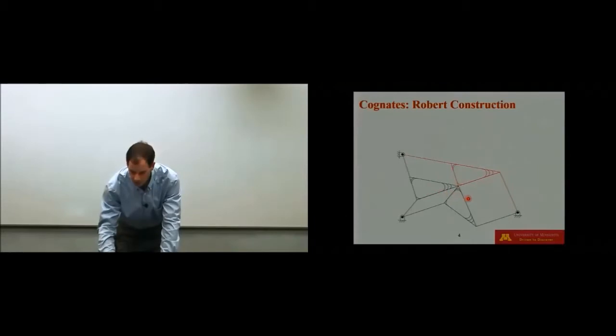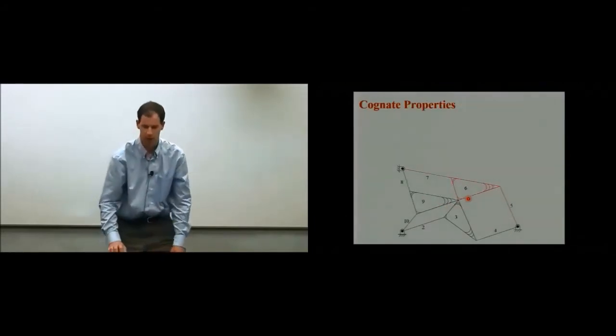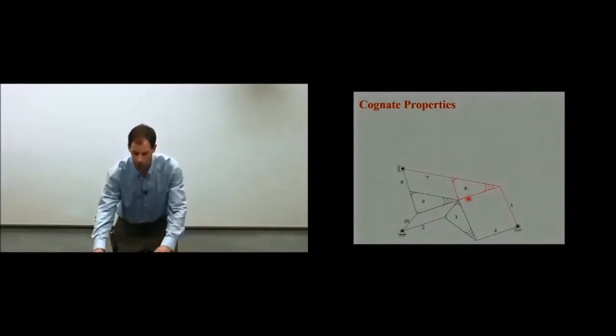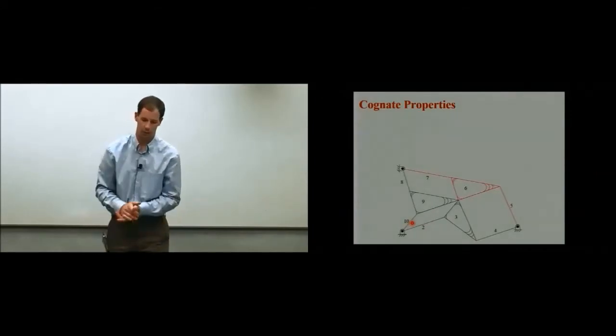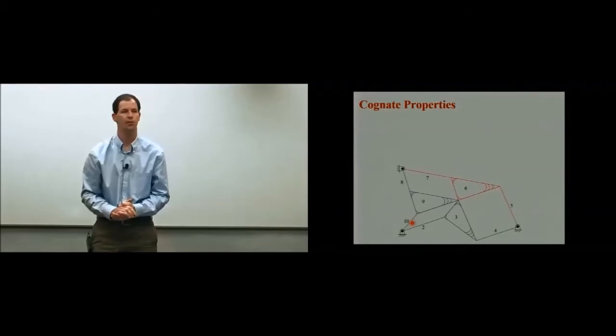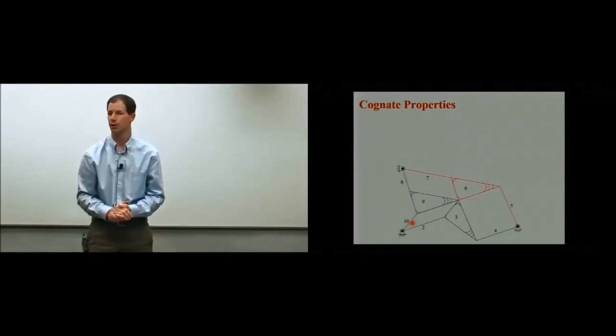And if you start counting these up, I now have a 10-bar linkage, starting off with my initial 4-bar, adding in 3 more for this red mechanism, 3 more for this guy right here. And again, ground counts as 1 all the time. So we've got a 10-bar mechanism. If we do a Grubler's equation on this, we've got -1 degrees of freedom, so we're over-constrained.